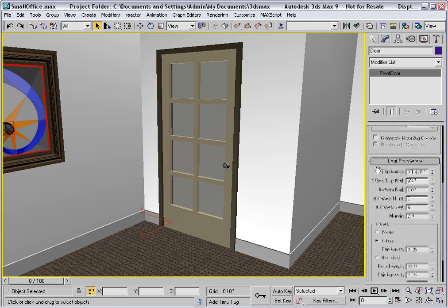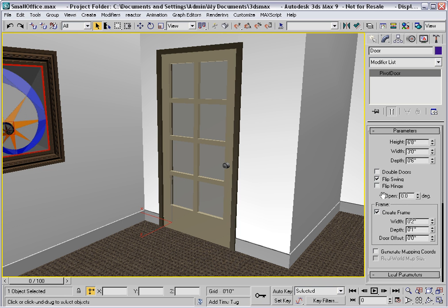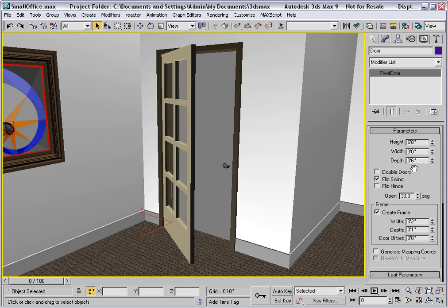What pivot doors are seriously lacking is support for doorknobs. If you open a pivot door, the doorknob is left behind. This is just annoying, because in a static rendering you could rotate the doorknob and position it just so. But it's seriously a problem in an animation, because you would need the doorknob to rotate seamlessly with the door if you were ever going to show that moving. I'll show you how to remedy this problem.